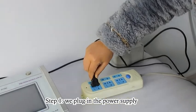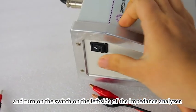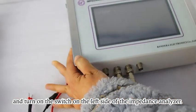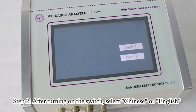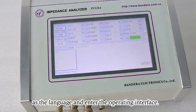Step 1. We plug in the power supply, and turn on the switch on the left side of the impedance analyzer. Step 2. After turning on the switch, select Chinese or English as the language and enter the operating interface.